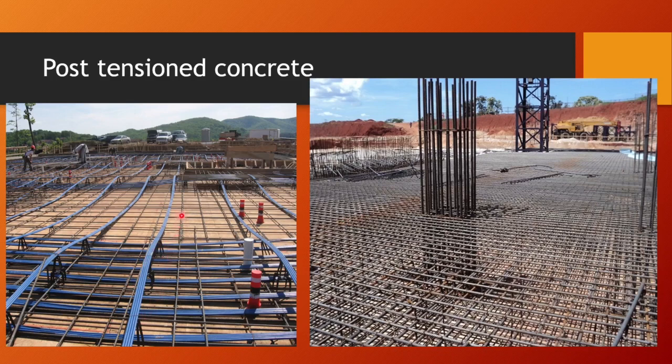And then on this example here, this is what we call post-tension concrete. As the concrete is poured in situ like this, all the steel sleeves and cables are just lying on the floor like this, as opposed to this, which is all pre-stressed. What you see is what you get there. They're all fixed in situ. There's no post-tensioning involved with this.